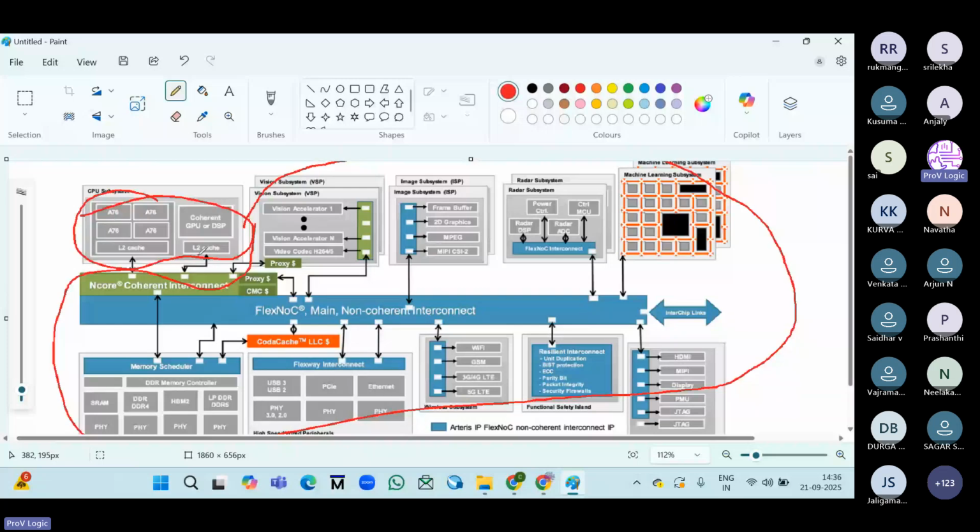So that's why, in industry, whenever you connect the core to hardware, we never verify those core test cases using SystemVerilog or UVM. SystemVerilog and UVM are used only to verify hardware description languages, that is Verilog HDL or even VHDL. But for processors, especially, we are designing using instructions, assembly language programming. That assembly language programming is never verified using SV or UVM. It is verified using C or C++.